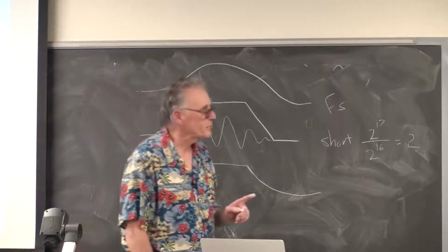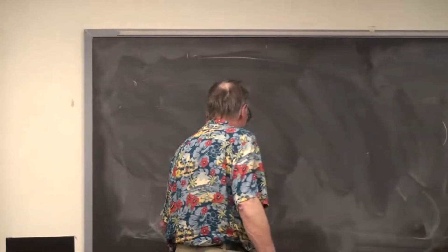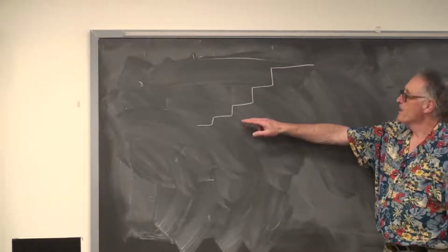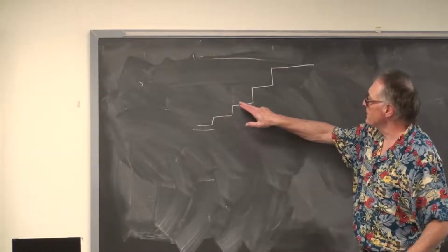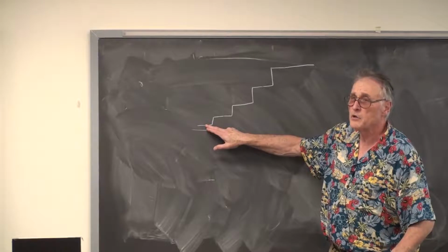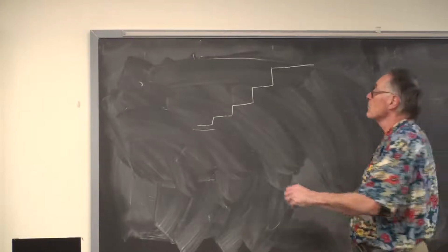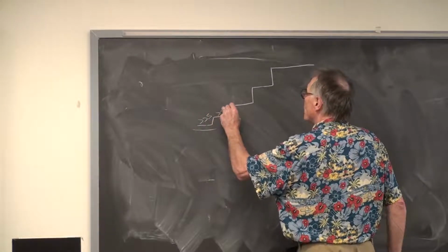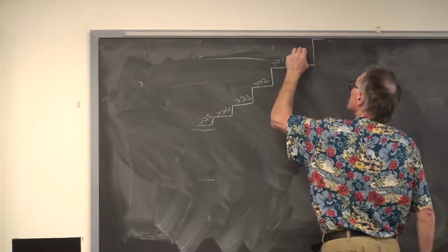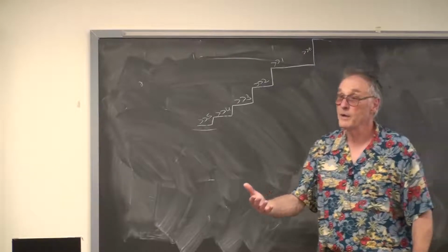However, there is one other option which is kind of interesting, and that is right shifting the whole waveform in small steps. So you start out with right shifted 5 bits, and then 4 bits, then 3 bits, then 2 bits, then 1 bit. So you take the sine wave, you right shift it a lot, you get a low amplitude. You right shift it 1 less bit, you get a higher amplitude by a factor of 2, 3 dBs. And so by right shifting less and less, so this is right shift 5, 4, 3, 2, 1, 0. By right shifting less, you get a higher amplitude by a factor of 2 every time. You get an exponential rise.